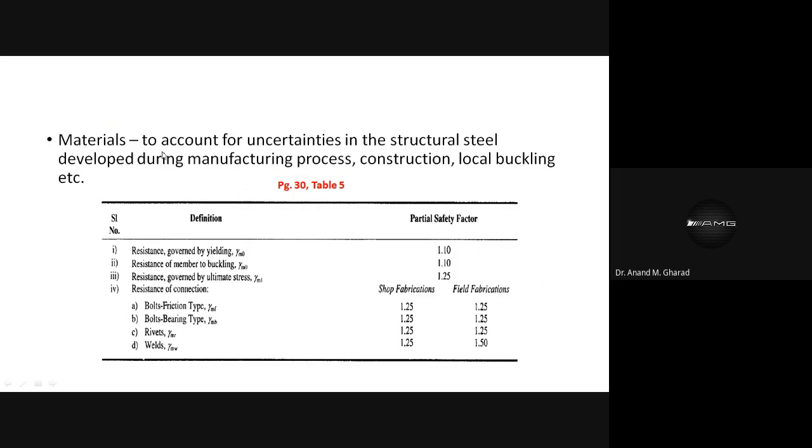देखो क्या होता है, देखो we are using the hot rolled section. Hot rolled section I have already covered, how it is manufactured, how hot rolled sections are developed, and keeping in view their limitations, you will find there may be distortion, there may be some kind of residual stresses, isn't it? So those manufacturing defects need to be considered while designing.